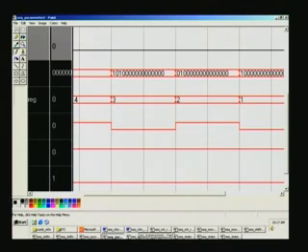This is a general question. You talked about always at positive edge, negative edge. How do you go about doing level triggering? The level is the same. You sense the level and immediately take action. It can be within the sequential circuit or outside it. If it is outside, you can use an assign statement, a mux statement. If a particular level is 1, immediately let the output change using an assign statement.